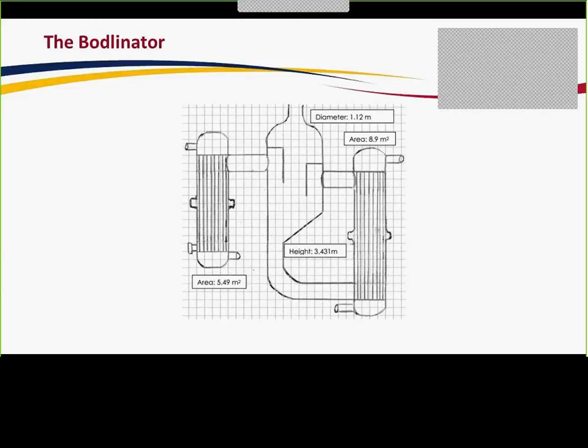the bottom of the second shell and tube heat exchanger, which vaporizes approximately 25% of it by pass using medium pressure steam. Again, as the liquid levels rise and the vapor rises, it again reaches another baffle and is disengaged using a mesh layer that further allows more vapor to come out the top. One of the main advantages of this system is the fact that there is a recycle incorporated into it, which helps improve efficiency and increases heat transfer rates.